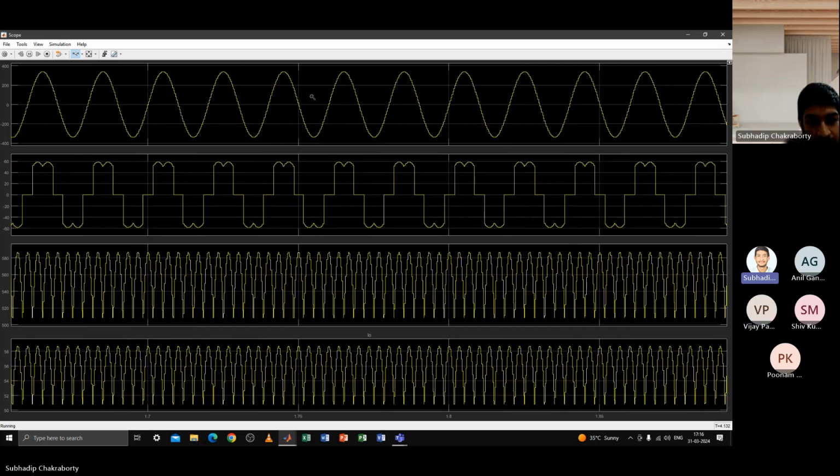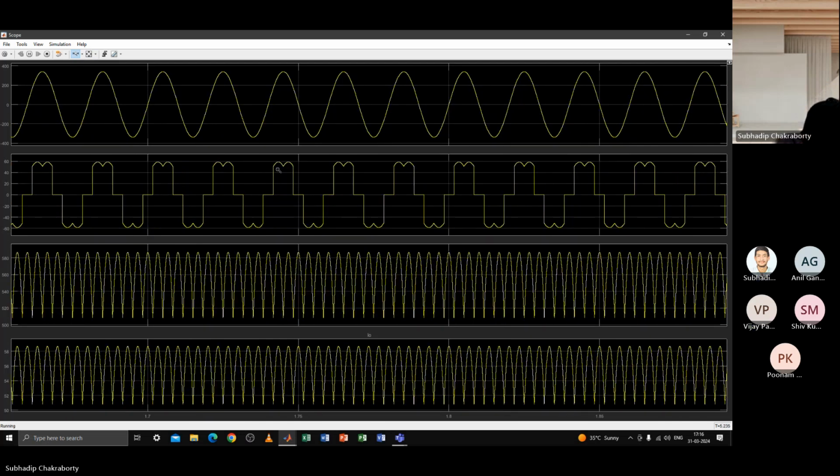So do you see any distortion in the waveforms? Yes. But you don't see any phase shift of the crest. Please understand. So if two waveforms of voltage and current are not having any phase shift, then their displacement power factor is 1. What is the meaning of displacement power factor? Displacement power factor means the shift of the fundamental of the waveforms.